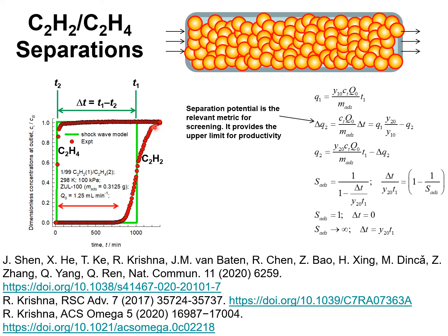For this purpose, we consider the experimental data for ZUL 100, shown by the red circles, and the simplest description of breakthrough in a fixed bed adsorber is afforded by the Shockwave model, wherein we assume that the concentration fronts of ethyne and ethene traverse the length of the fixed bed in the form of shock waves.